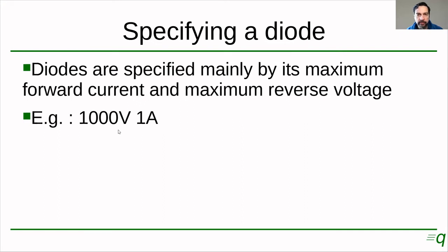This is something that is actually done on purpose on some circuits and with some special diodes. But normally you should not exceed this voltage in your circuit. Basically, that's the maximum voltage that the diode is going to block in reverse. If you put more than 1000 volts on this diode, the diode will allow current to flow.